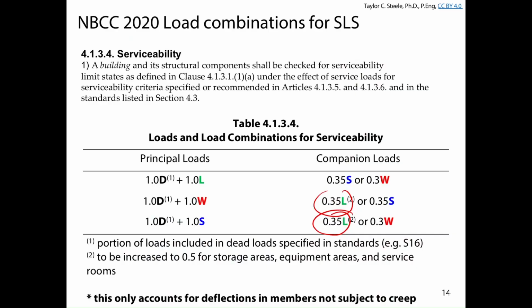How much of the dead load do you think contributes to the deflection that may cause delamination of floor tiles? Not really intended to be a trick question, but it's just a question about what the order of everything being built is. You're building stuff, and in lecture 3, I showed you the example construction sequence of a structure. When the structure is done in terms of the steel contract work, you've got the steel framing there, so you've got all the weight of the steel framing. The steel deck is there, so you've got all the weight of the steel deck. And then the concrete trades come in, they pour the concrete floor, and so you've got all the weight of the concrete floor.